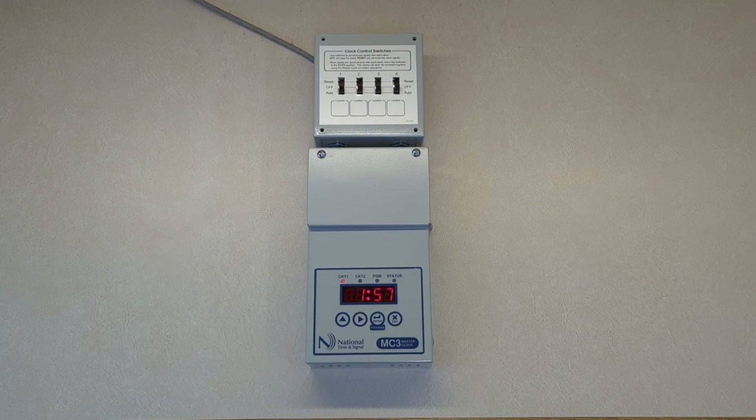To enter the tech menu where we will set the circuit type, press and hold the program button for 10 to 15 seconds. Keep holding the button when you see C1, then you'll see the time flashing, keep holding. Now you'll see C1 and some numbers. This is the menu you want.